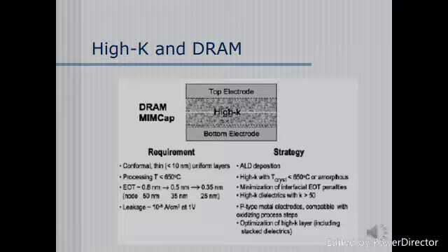EOT values have to be very minimal also, at around half a nanometer to 0.35 nanometers, with leakage current no less than 100 nanoamps per centimeter squared at 1 volt. With these conditions, the promising dielectrics mentioned before change when trying to achieve these high aspect ratios, decreasing their constants. And with incredibly small EOT values, optimizing electrodes and dielectric/electrode interfaces is very important to maximize the EOTs. With a metal with a high work function, this problem will be solved, if not for the complexity of finding the right metals suitable.